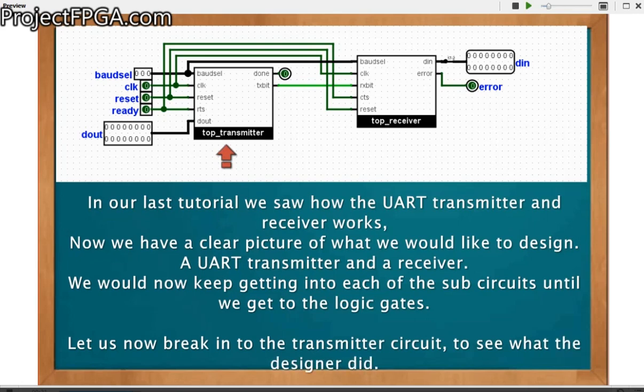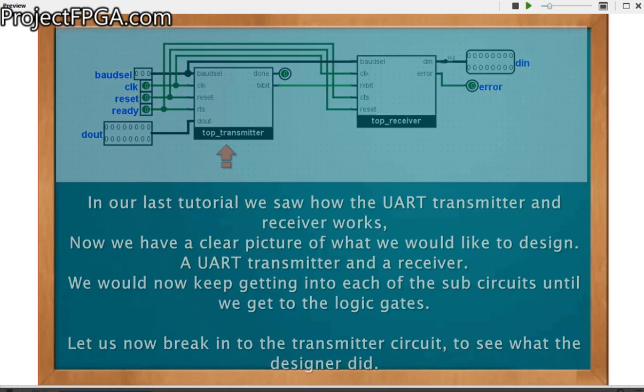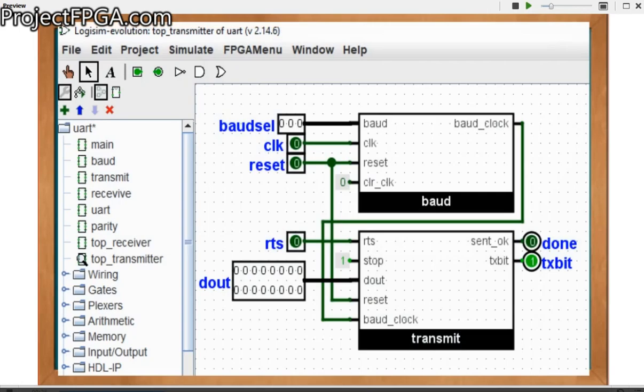Let us now break into the transmitter circuit to see what the designer did. Inside the transmitter are two other sub-circuits, the main transmitter and the baud generator, which we previously discussed. The baud generator generates the clock signal, which is used to synchronize the transmitter, and this is the baud clock.